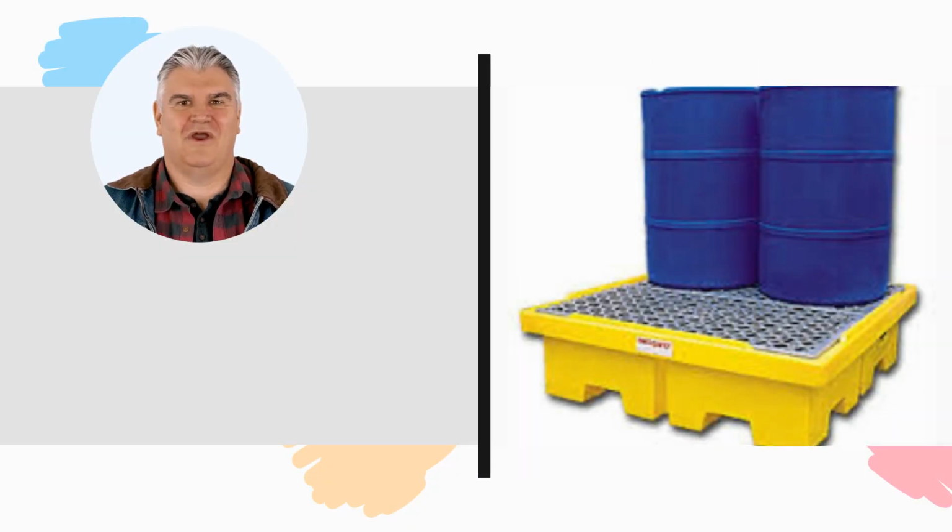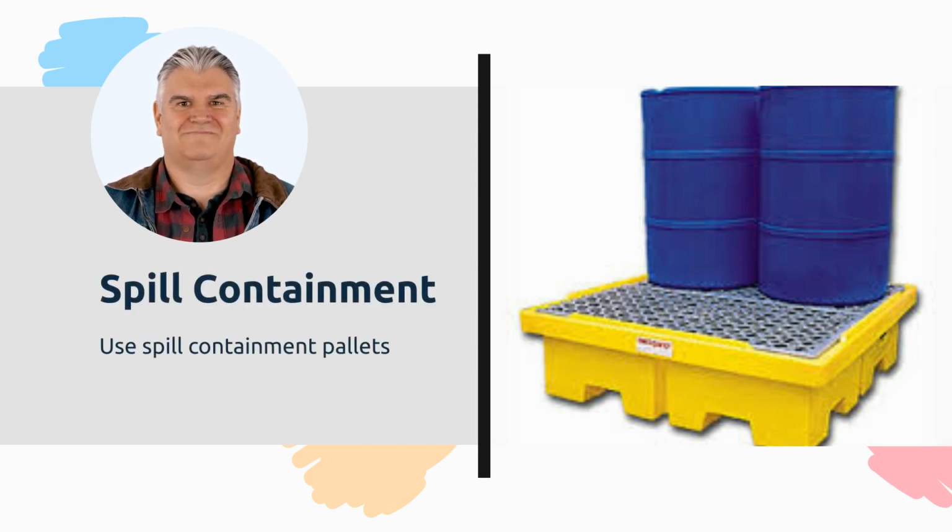If we need to store totes or drums inside the facility, we need to make sure they are put on the spill containment pallets so we do not have a potential harmful release if a tote is punctured or leaks.